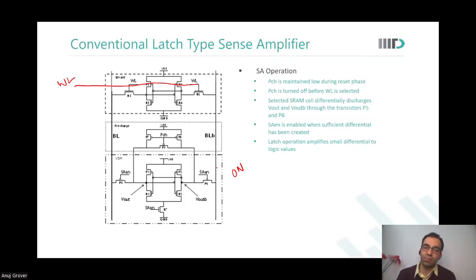Now, yes, sir. After that, that was my doubt, sir. If I enable my sense amplifier enable, I do understand there is a PMOS, and I'll be able to run my values into the central node, I mean Vout and Vout bar in this case. So after that, does that happen in parallel? I see it's coming from bitline and bitline bar, and it's directly getting dumped into the ground.